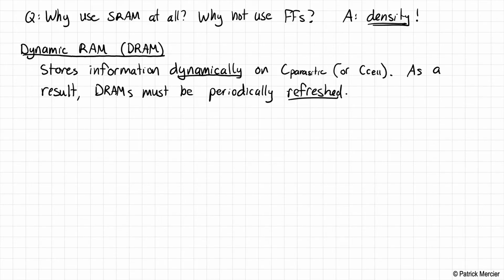So it turns out that DRAMs are extremely simple conceptually to implement. In fact, we can build a DRAM with 1 transistor, so we'll call it a 1T DRAM cell. And perhaps you already have in your mind what this 1T DRAM cell might look like. The basic idea here is we have the same overall array structure. We have our word line.